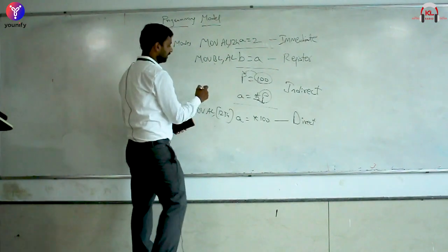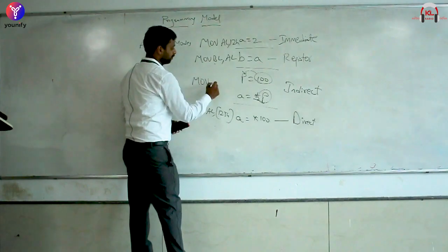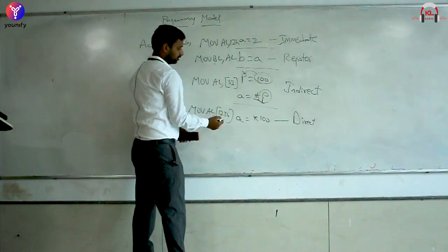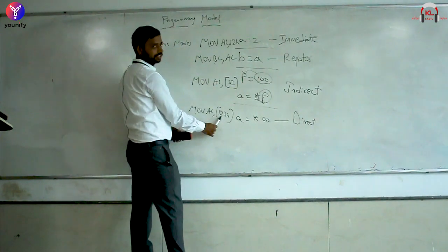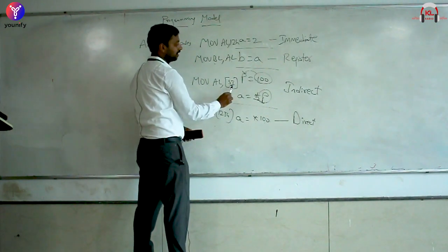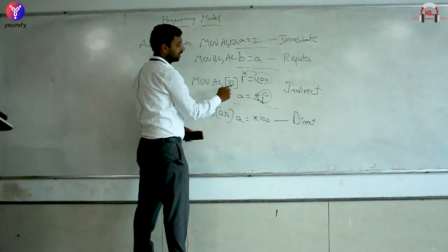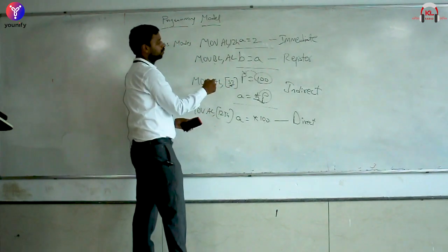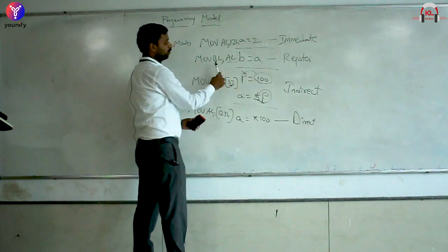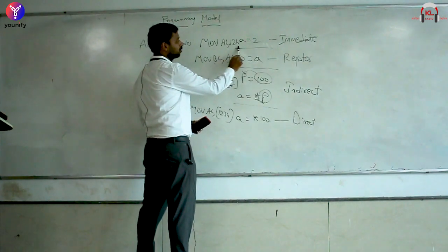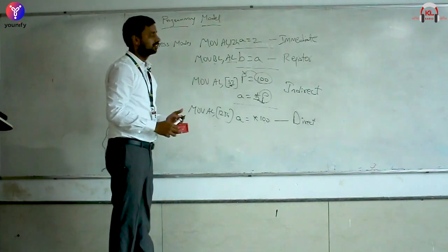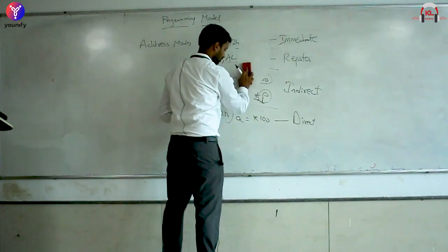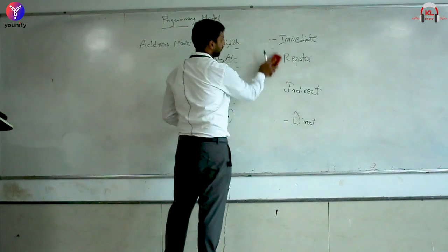So we'll just work on the details and we'll go into it. MOV AL, maybe a register. So here we are addressing the value directly and storing it here. Here we are pointing the address using a register. So this register has an address which will bring the value to AL. Here the contents of AL move into BL. Here the value 12 directly gets assigned to AL. So these are the addressing modes and the equivalences that we have already seen.